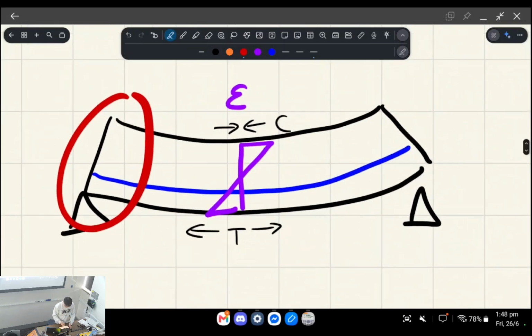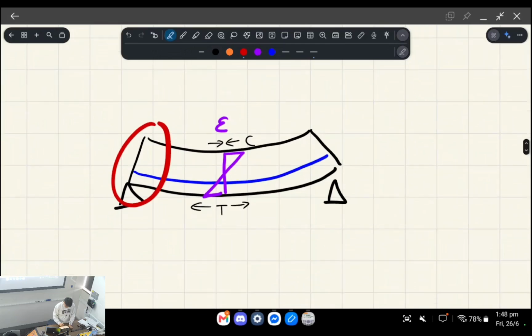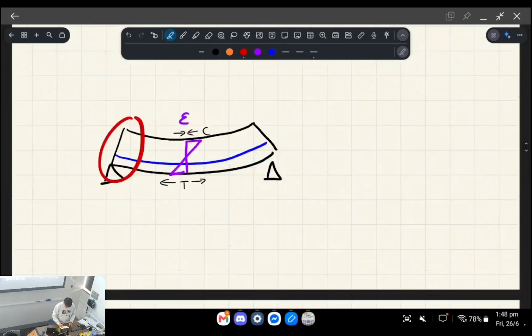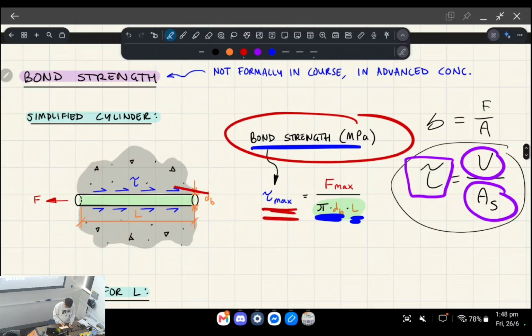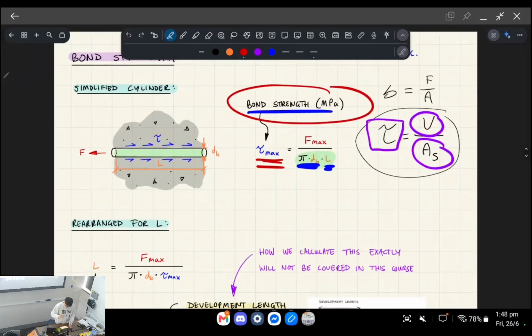So this is a composite material, right? Reinforced concrete is a composite material. It has two materials, right? It has concrete and steel. And for them to basically move together as a beam is bending, we say that there needs to be enough bond strength, okay? So essentially, there needs to be enough bond strength to hold these two materials together as your beam or whatever is experiencing bending. Okay, so that's why it's important to have enough bond.